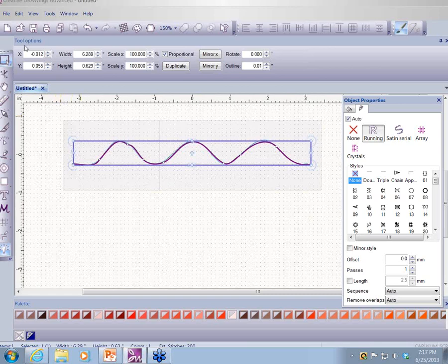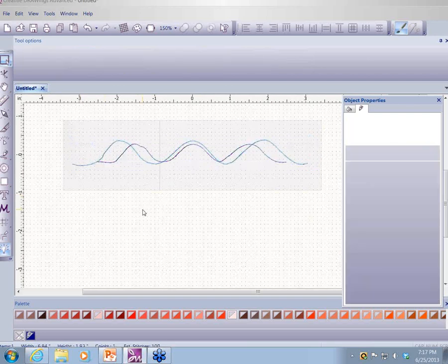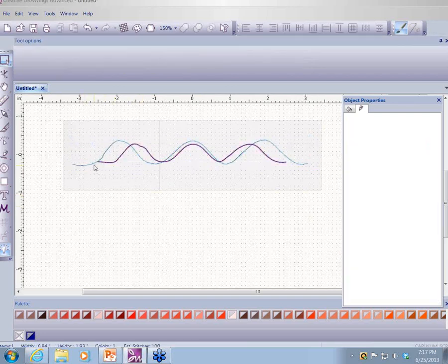Right away when I click onto that, I get my tool options open again. Now I know from measuring the pattern and measuring how wide this is going to be that my scallop is actually too wide for that wallet. So I'm going to change the width to 5 inches. I'm just going to type a 5 in there and come down here, and I'm just going to click, and do you see how that changed? Now you can see it's a lot smaller than my backdrop here, my image. That's exactly the way I want that to be.